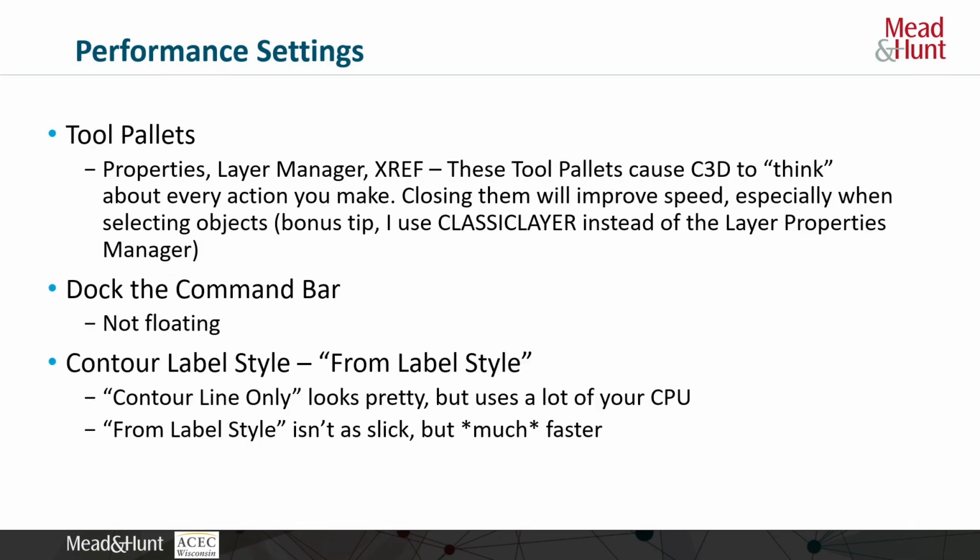Your tool palettes are all incredibly helpful, especially properties. I leave properties open all the time, but with those open, all of those are live, and your drawing is thinking about all the information inside of every tool palette. As you're working on items and selecting things, your properties has to think about everything you're clicking on.